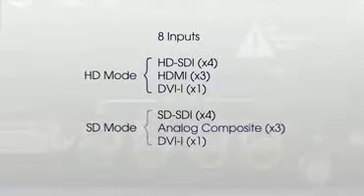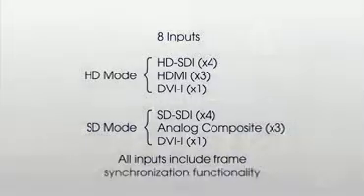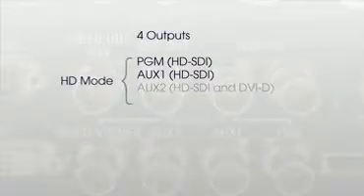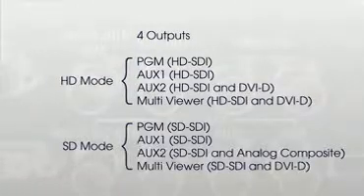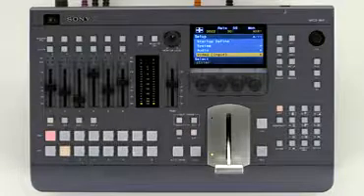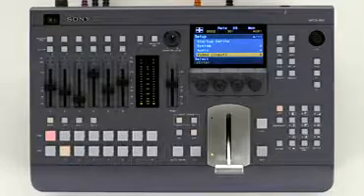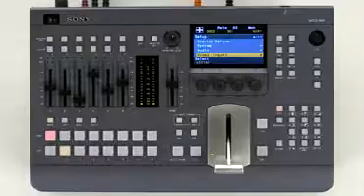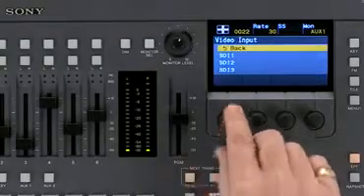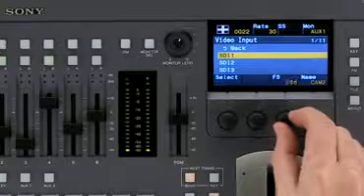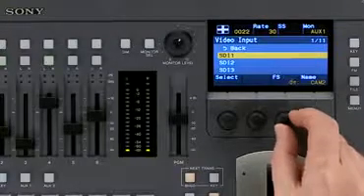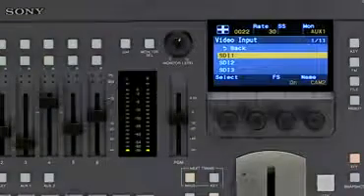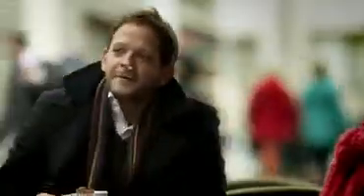Connect all inputs and outputs to the rear of the MCS-8M panel. Having specified the image signal format and aspect ratio, you can simply gen-lock cameras and begin operations. However, for untimed signals, it may be necessary to set the input frame synchronization. This can be used to synchronize all video signals coming into the switcher. As the input synchronizer is turned on, we can see that the signals become correctly timed.